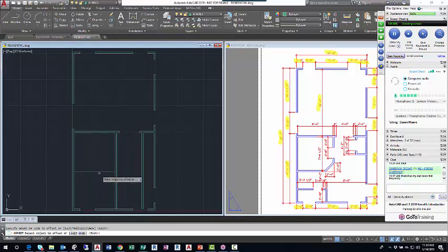So there's the bottom edge of that bottom wall, or top edge of that bottom wall, if you will. All my walls are 3.5. So offset 3.5, enter. I'll left click that new horizontal line, left click, move down the screen and left click. Escape.